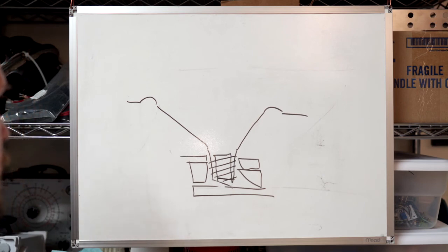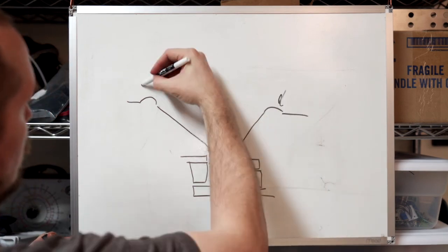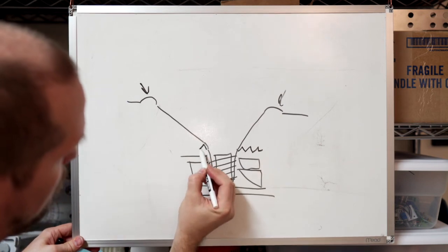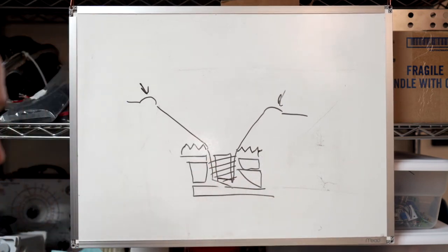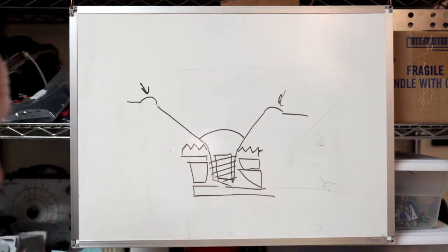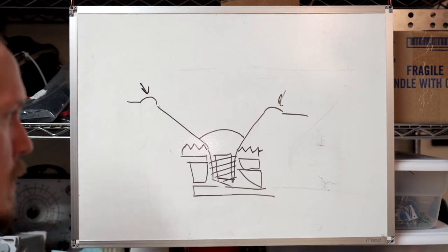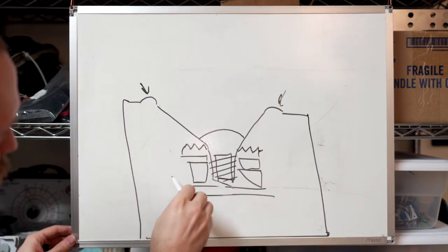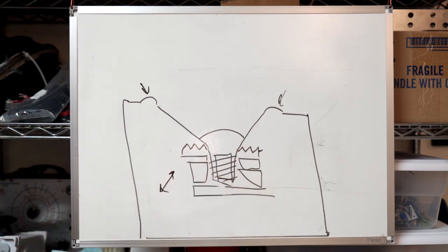And so you've got mechanical dampening. So these right here, the surrounds, mechanical dampening right there. You also have a spider here, like that. This is mechanical dampening. And whatever the cone is made out of will be designed to vibrate at the frequencies it's supposed to be operating at, but it will probably be designed to not vibrate at the frequencies it's not supposed to vibrate at, and so it's dampened slightly there. It's also going to probably be, let's say, in a cabinet, and the pressure of the air in the cabinet will also dampen the woofer somewhat.